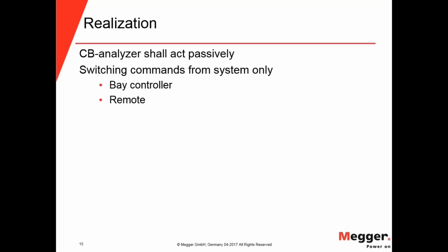However, in this kind of test, when it's a live condition, you cannot do that. So the circuit breaker analyzer shall act passively, which means that you have to use the bay controller or remote control room to initiate all switching commands. That's important since it's considered as live.